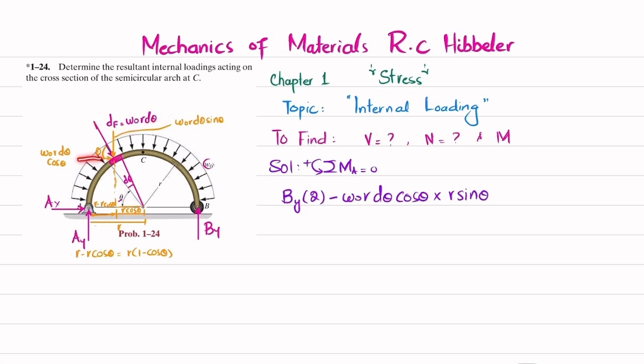So for taking the net force over the entire curved beam, I will integrate it, so it will be integral of 0 to pi. Clear? And the third force will be this df sine theta, which is W naught r d theta sine theta, and now the perpendicular distance is r into 1 minus cos theta, and it is also producing clockwise moment, so it will be negative. So I will write minus integral of 0 to pi W naught r d theta into sine theta multiplied by r into 1 minus cos theta, and the sum of all moments about point A is equal to 0.